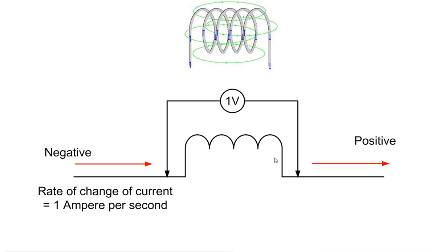Suppose now we try to decrease that current. If we try to decrease the current, the magnetic field will collapse, energy will come out of the magnetic field, and a voltage will be induced into the inductor, opposing the change we're trying to make. So if we're trying to decrease the circuit current, the reducing magnetic field will induce a voltage which will try and maintain the status quo of the current in the circuit. So with inductors, there is always this delay in current.